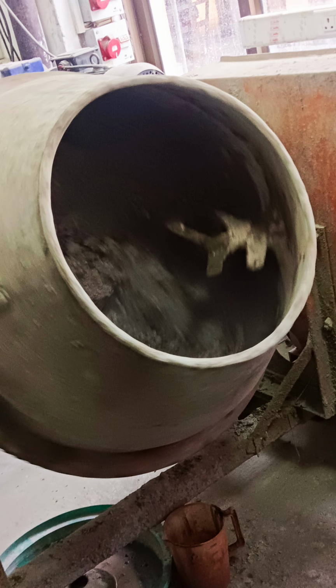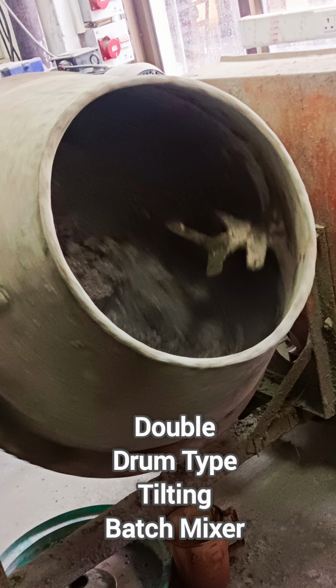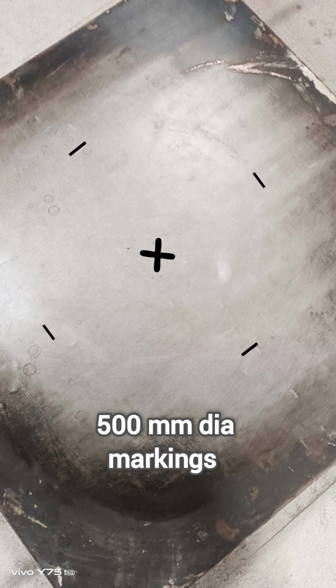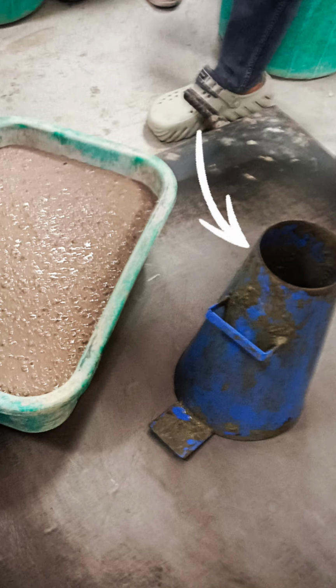Firstly, we have prepared the mix in the double drum type tilting batch mixer, considering all the proportions of the self-compacting concrete. After preparing the mix, we have oiled the plate, and this is the cone, which is filled in one go.